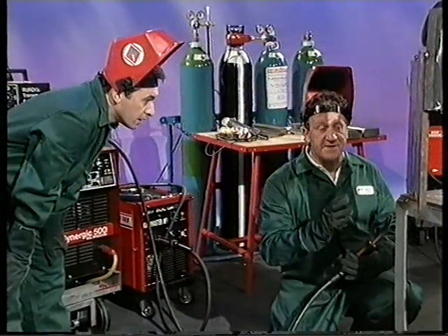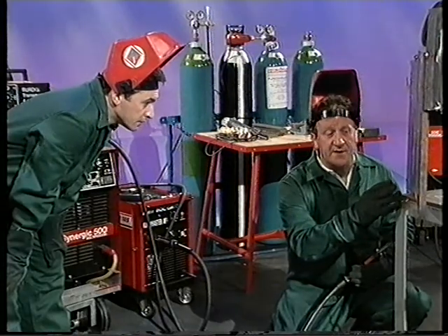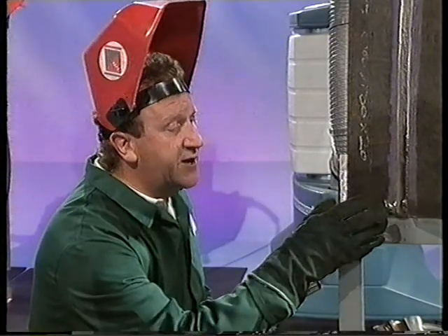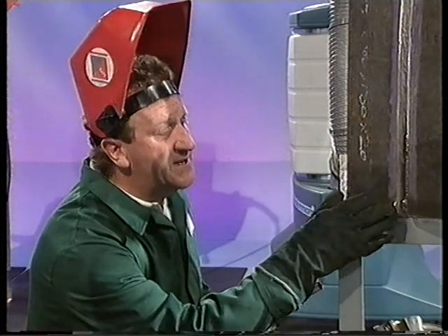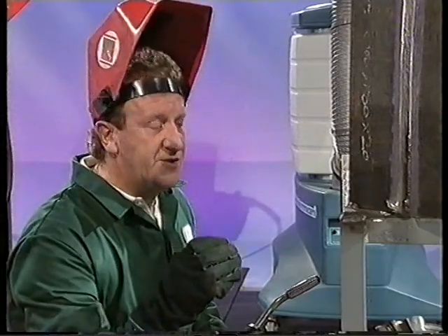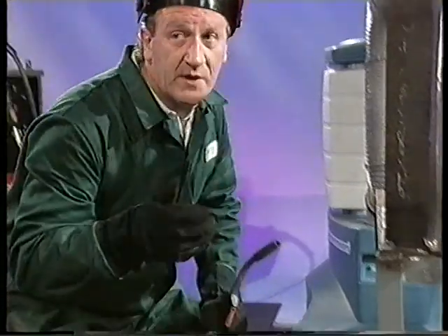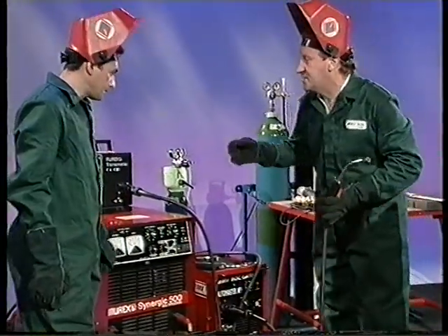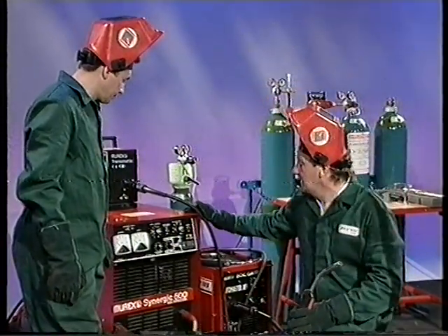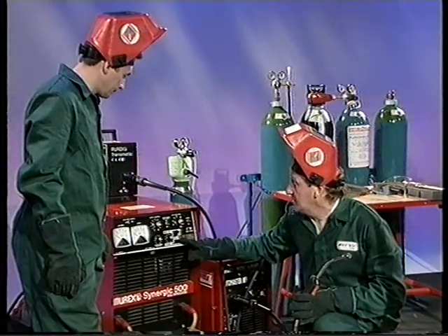Right, smashing. Okay, well, the next part of it is the weaving to fill up the joint itself. The dip condition that we use there is going to be perfectly good for the root run. If we were to get these quite complicated weave patterns that we're going to need to fill this joint out, there is a risk of lack of fusion. So we'll use synergic pulse, where we're going to be using, in effect, an imitation spray transfer mode at very low amperages. Now, on the machine, we can select that on the button here.